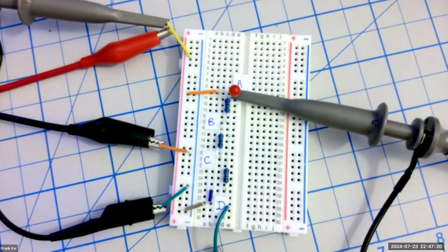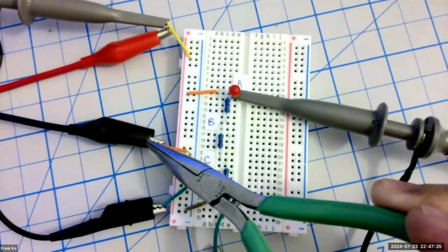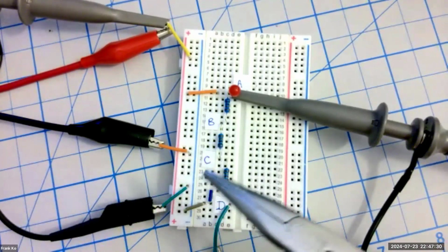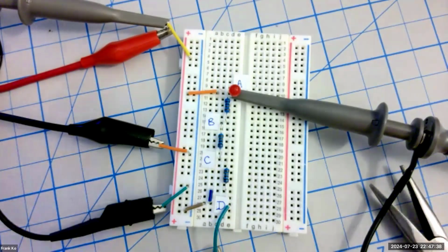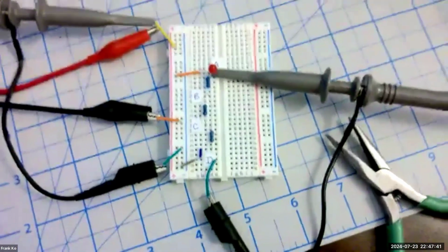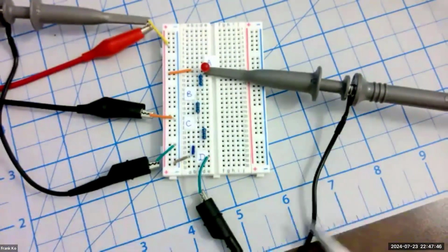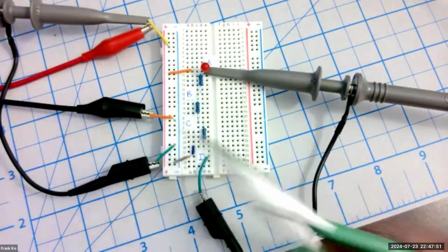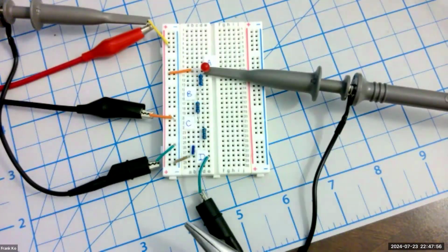Now, these are my ground connections. So each probe has a ground connection. So the probe has a black alligator going to the blue rail. The function generator has a black alligator going to the blue rail. And then, of course, this probe also has a black alligator going to ultimately ground on the blue rail. Bring this up just a little bit. You can see this just a tad more clearly on my 3 grounds. So here's the ground of this probe, here's the ground of this probe, and here's the ground of my function generator. They all have to make their way to a common ground point, which is my blue rail.